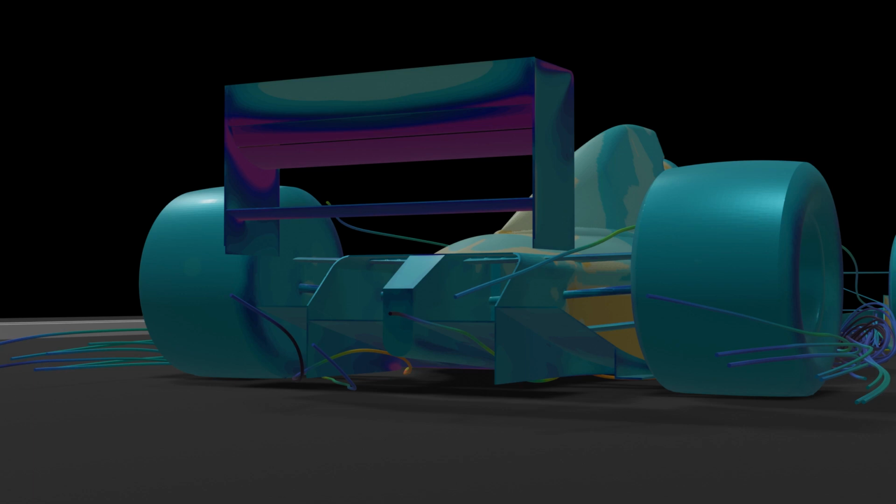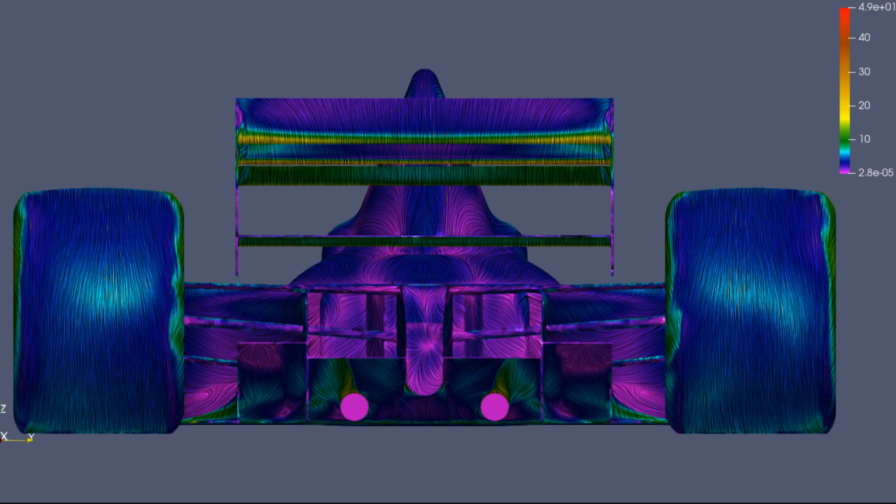However, placing that profile on the back of the car made 400 newtons disappear into thin air. Having developed a decent feeling for why this profile worked, I tweaked the profile but could only get back to 1300 newtons. Further tweaking didn't make things better. Considering full car simulations take a day, this is the number that I had to be satisfied with.